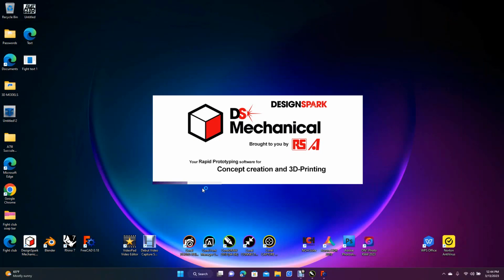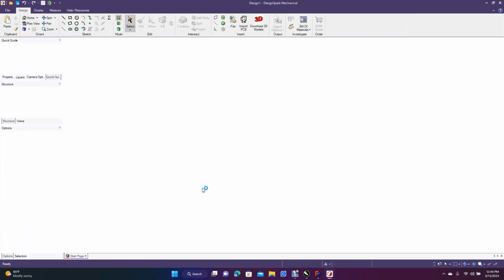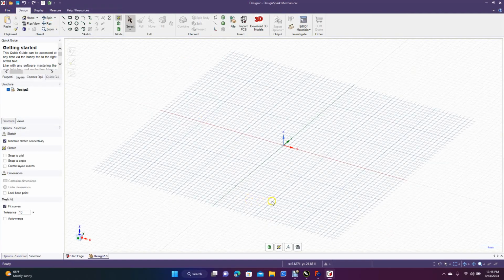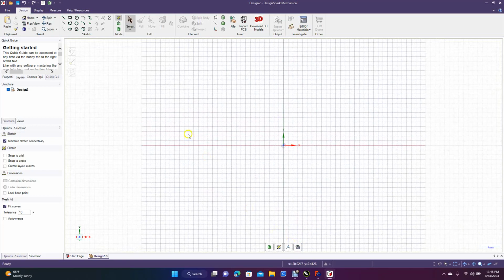Now I'll show you how to do this. We're going to create this in millimeters, but when we specify dimensions, we're going to put in IN. So it's going to work in millimeters, but it's going to be the appropriate size in inches. So we'll go ahead and make that flat there.